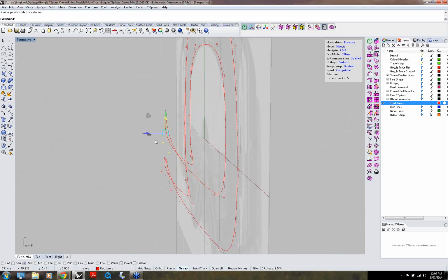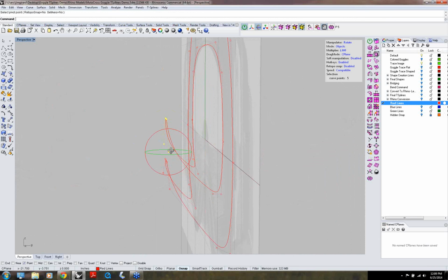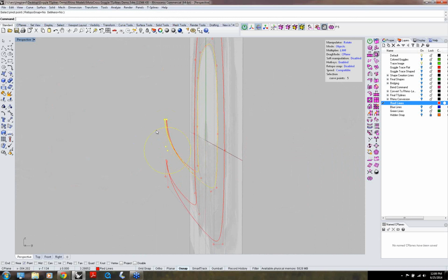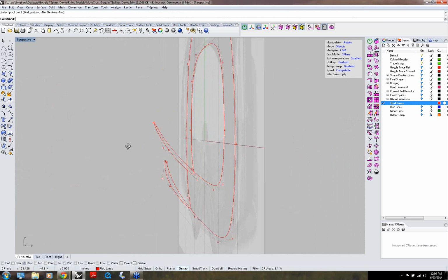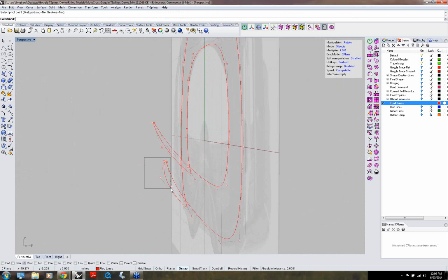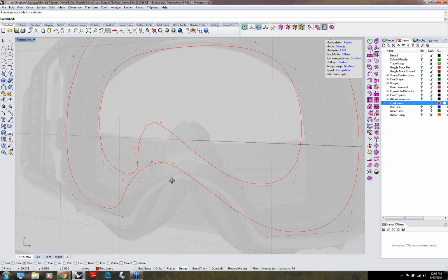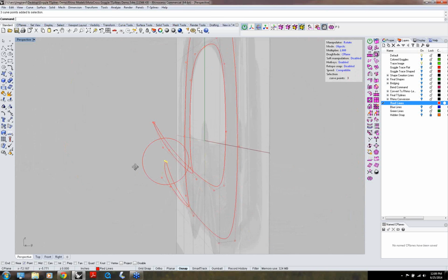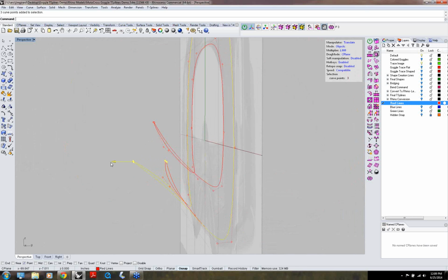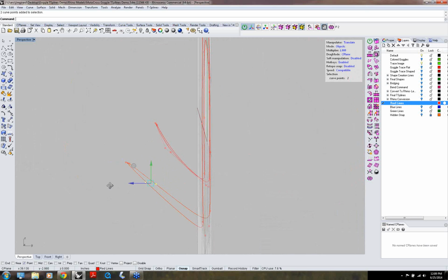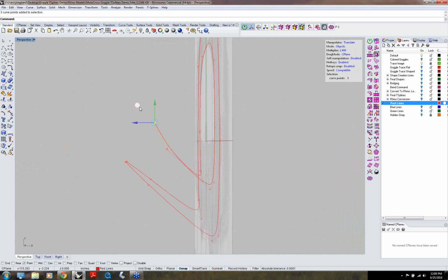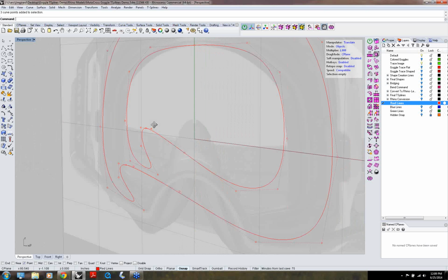Now in T-Splines, you can set where your manipulator goes by hitting the E key, or T key, and then moving over to that point, and then the E key, which is rotate for the manipulator, I can start developing my nose piece where I want it. So again, I can pull this bottom line one out, go to my translate, pull it further out, and start shaping what I want to do for my nose piece on my mask.